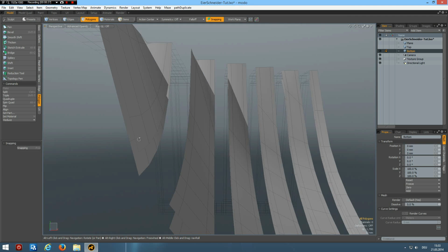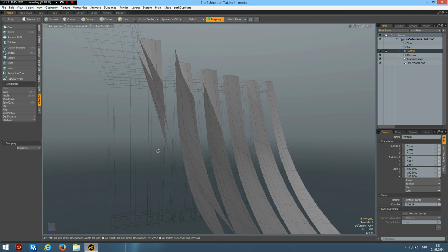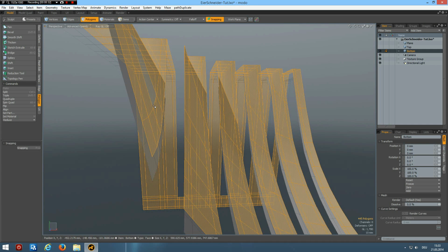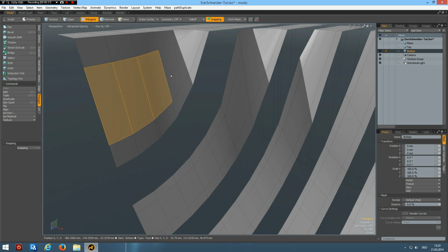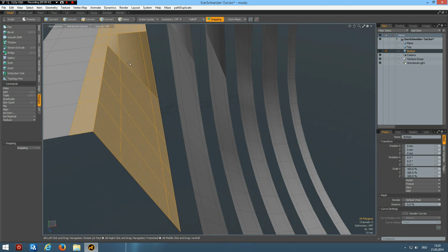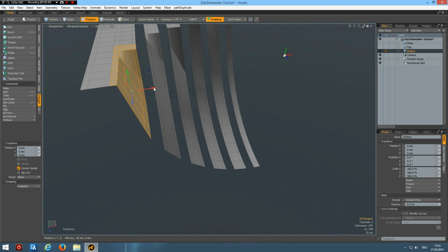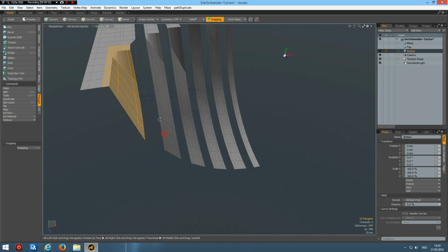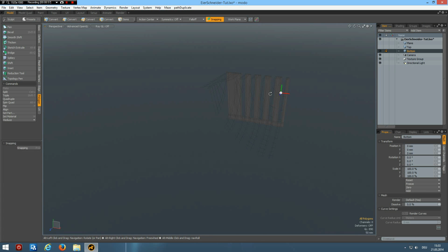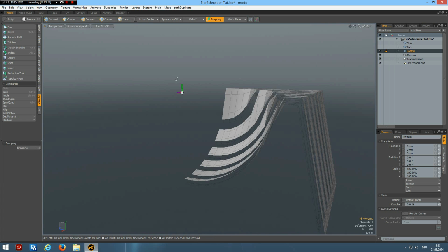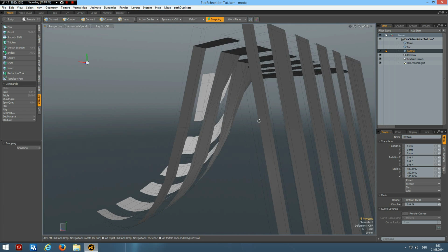Now we have another area which will be a bit small, so I select the top here, hide it, select the shift up arrow once more, W key, and move this back a bit. Yeah, -20. I like to use numbers which I can remember. One never knows. Now I press F and flip everything, unhide, and now I should be able to connect everything together.